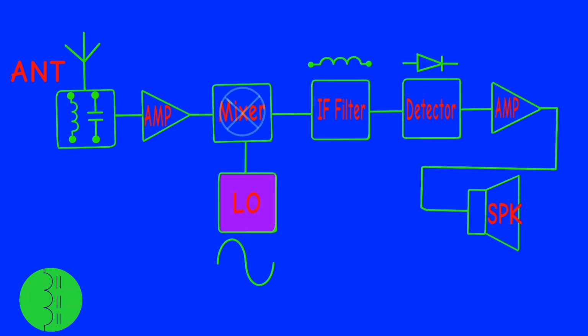4. Local oscillator, or LO. Purpose: The local oscillator generates a high-frequency signal that is mixed with the RF signal to produce the IF signal. Function: The local oscillator typically operates at a frequency that is either above or below the incoming radio signal by a fixed amount called the intermediate frequency. For example, in a typical AM radio receiver, the local oscillator might be 455 kHz higher than the incoming signal. Characteristics: The frequency of the LO is variable in many radios, as it is tuned to match the frequency of the incoming signal and create a stable IF.